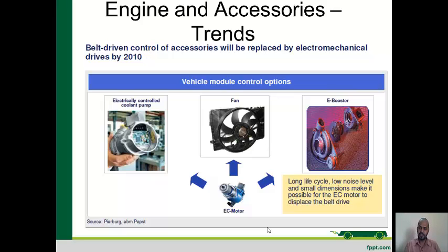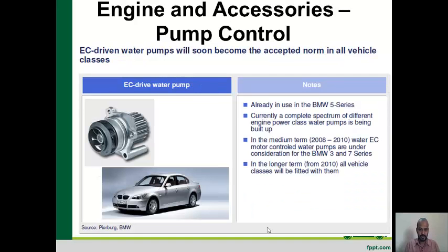As of now we are using a mechanically operated turbocharger driven by the exhaust gas, but a lot of research is going on to use an e-booster or e-turbocharger, and an electronically driven water pump. Present vehicles are using a mechanical water pump, which is normally coupled to the engine crank belt.